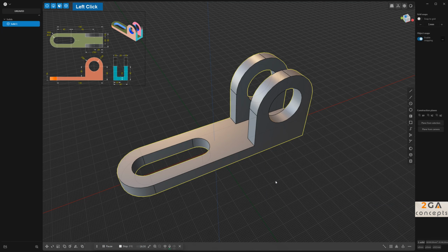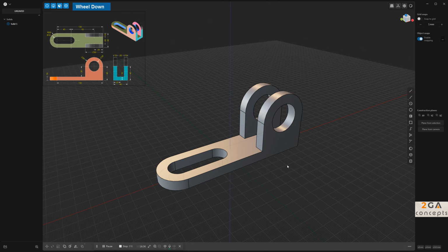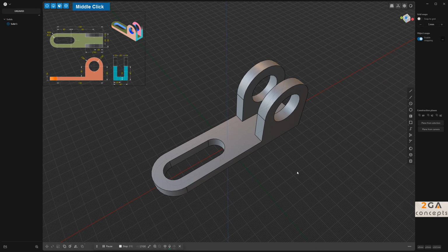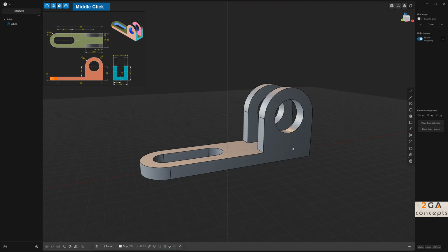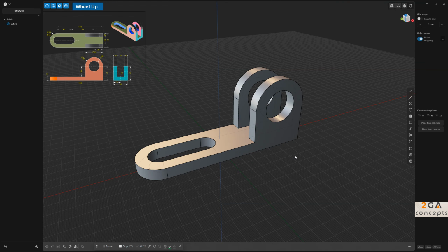F. We hit that, and look, you get rid of those extra edges, because that's a simple shape, right? If you're creating a complex scene with several shapes and you leave edges hanging around, it's going to be a real problem at one point if you export that, for example, in another software like Blender or something else, and you're going to end up with troubles, with so many edges hanging around on your body, your solids. Okay, so see you in a bit for exercise 6.